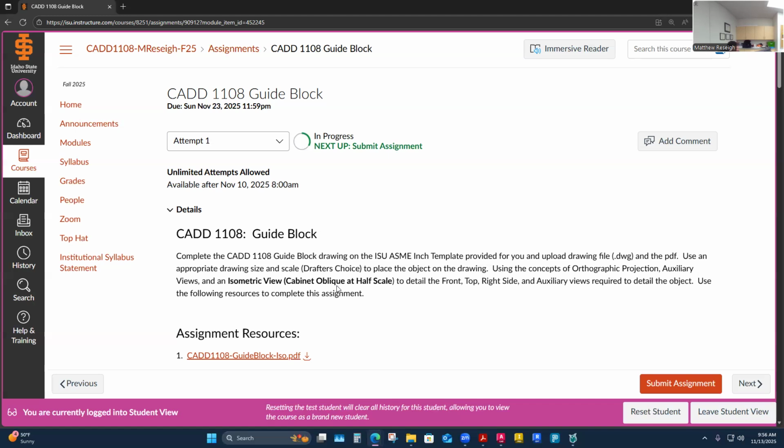A general oblique just depends on the particular part and what projection angle I establish, and whether I'm going to do full scale depth, or half, or 3/4. To me, it's kind of like a cavalier oblique, only cavaliers are generally full scale, but even on a general oblique I can draw at full scale.